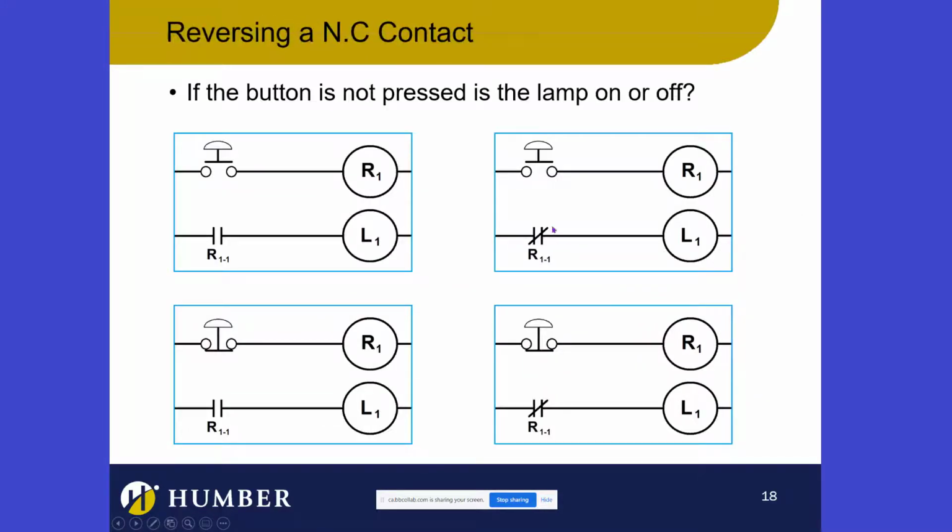So we're talking about some pretty cool stuff here about how to actually say logical statements and put them into a ladder diagram, because often when you're designing stuff, you're thinking, okay, I need it so that if the temperature goes up, the heater comes on. And if somebody opens the door, but if the temperature is low, then the heater should come on. But if someone opens the door and the temperature is high, then the heater shouldn't come on. Something like that. So now get this. This is a pretty cool example here. Let me walk through this with you guys.